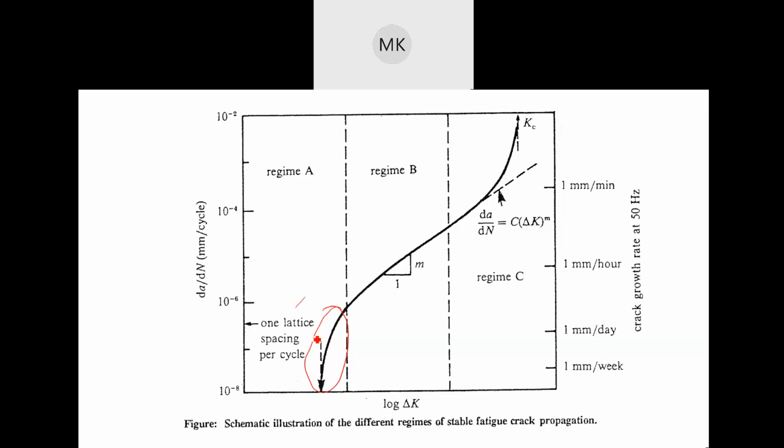When it goes beyond certain grains, that's when you know that's the major crack that is going to continue to failure. And then after that, it goes from picometers to about nanometers in your stage two, which is your Paris region, where they have a constant rate at which the crack is growing, and it goes up to a few microns per cycle.